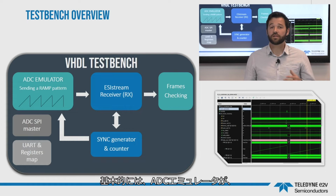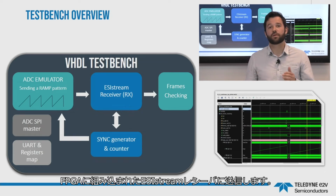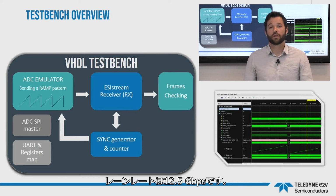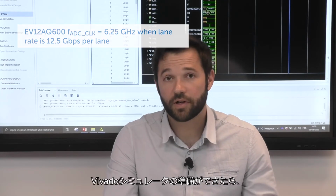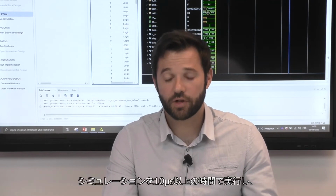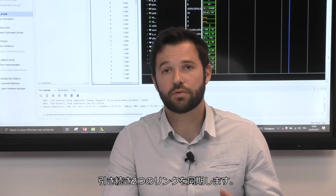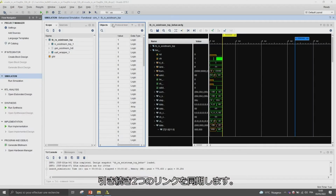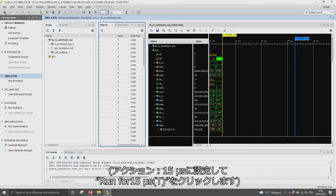Basically, an ADC emulator is sending a known ramp pattern on each serial lane to the ESIstream receiver embedded in the FPGA. The lane rate is 12.5 gigabit per second per lane. When the Vivado simulator is ready, run the simulation for more than 10 microseconds to simulate the two successive link synchronizations. I set here a simulation time of 15 microseconds.